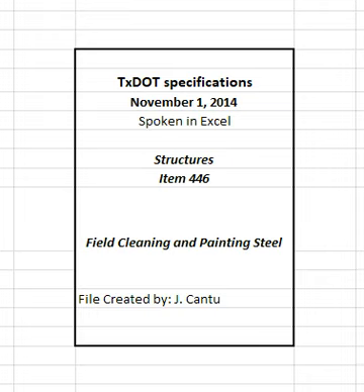4.7.4.8 Workmanship. Perform all painting with skilled painters who can adjust equipment and application techniques as dictated by the type of paint, weather conditions, environment, and size and shape of the surface being painted. Painters who, in the opinion of the engineer, do not adjust equipment to apply coatings in a uniform, full wet coat free of runs, sags, holidays, and overspray will not be considered skilled painters.